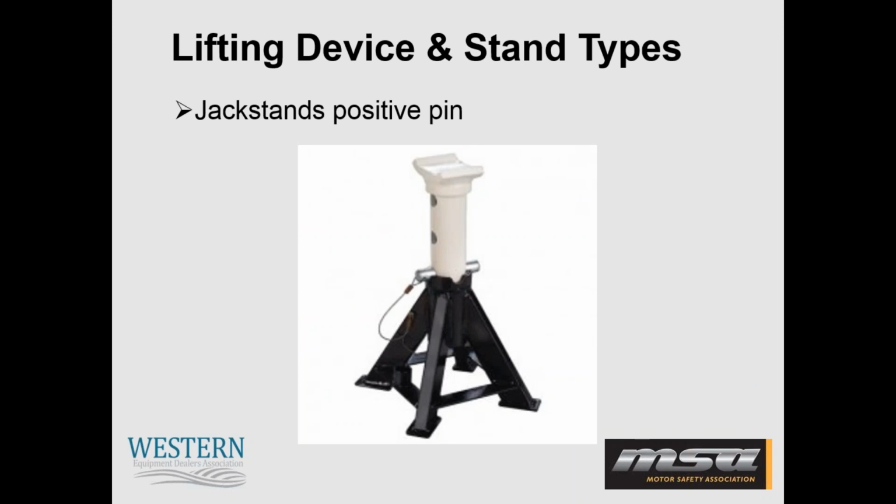The next type is a positive pin, and we see these more so in the heavier duty applications, which could be those combines or large pieces of industrial equipment. But a critical fact with this type of jack stand is that you need to use the pin supplied with the jack stand. And you can see on the picture there's a lanyard that holds the pin in place so that it doesn't disappear. Too often I've seen where people have substituted a bolt from their shelf in place of the pin. And that is not effective because these jack stands are only as strong as its weakest link, and you need to use the pin that originally came with that device.